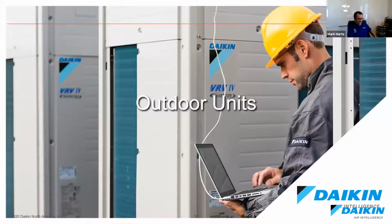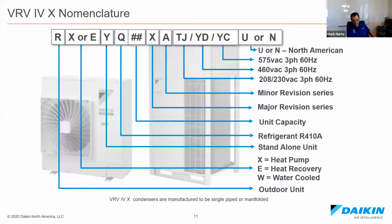So we're going to start with the outdoor units. As you see, this technician has his laptop hooked up. There's several things we can do with the laptop. Now, as far as the model numbers of our outdoor units, we make two styles, if you want to say that. We make a heat pump and a heat recovery. A heat pump is a straight heat pump. It's a two-pipe system that you can heat or cool.